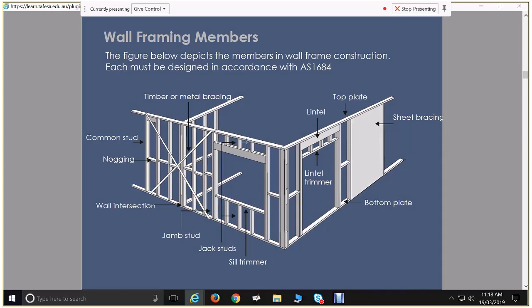So pretty much any scenario of fixing a lintel in there is going to compromise the strength of your stud, even if we're seating the lintel between our studs and putting bugle-head screws through to help pick up that lintel. Providing double studs means that we can chop one of those studs off short. So our jamb stud, we chop that off short, our lintel sits on top of that, and then we fix our lintel into all of those pieces of timber. It makes a really nice seating arrangement for that lintel, and it's really easy to fix in a very strong manner. So by and large, that's what you do: you say double studs to all openings.